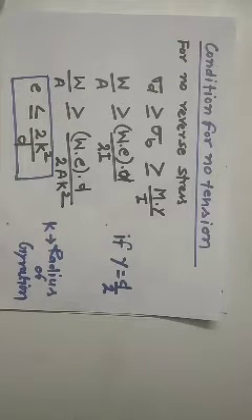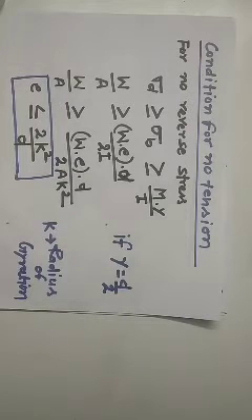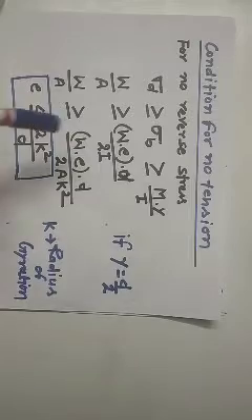We will discuss the condition for no tension. Since we know that masonry or a column designed for taking compressive load is not capable of taking tension, we have to ensure that no phase of these structures develops tension, to avoid failure due to cracking. And this limits the eccentricity E to a certain value, which we will discuss here.